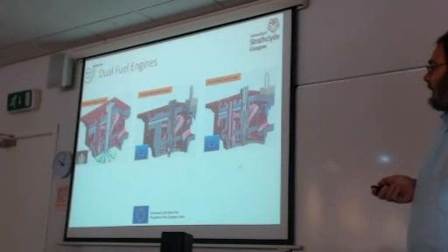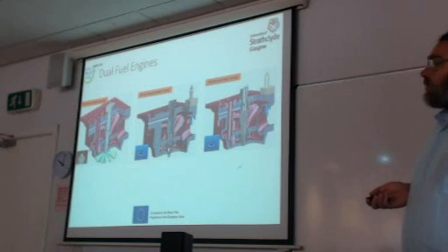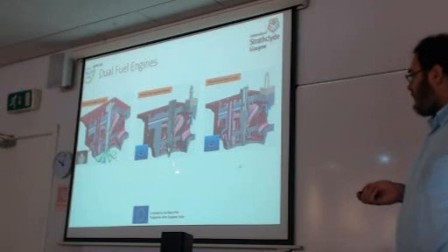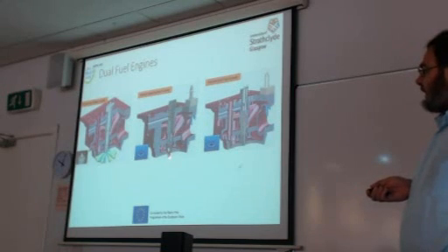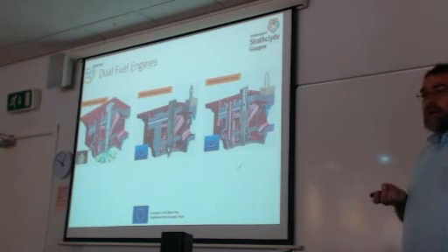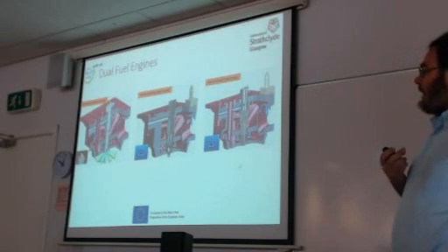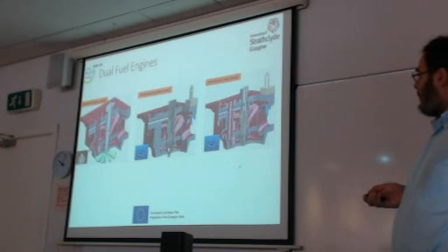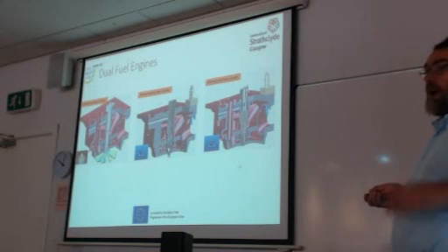And then we have the spark ignited concept. What happens here? The fuel is injected in gaseous form, so we have natural gas injected either in port injection or directly in the combustion chamber, and then the combustion starts by a spark plug. There is a spark plug installed in the cylinder head, and by initiating a spark, it provides the initiation for the start of combustion.